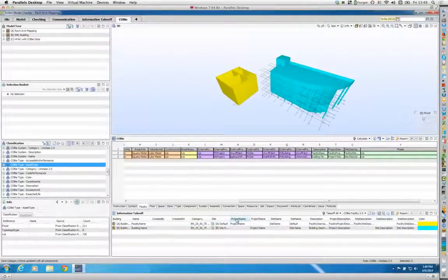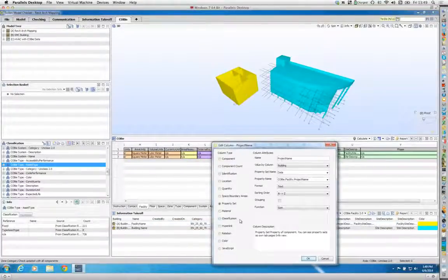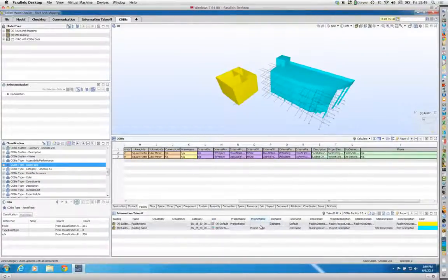You'll notice that we've got another one here which says project name, because this is not actually picking it up, and we haven't scripted it for every different type of application, because it would be harder work to do that. What we've done is added another column here called project name. So this is the odd occasion where we've got two field names the same. This is our location for where it's grabbing it from Revit, which is the data COBie facility project name. And this is the value where it's grabbing it from the JavaScript, which just picks it up from different areas.